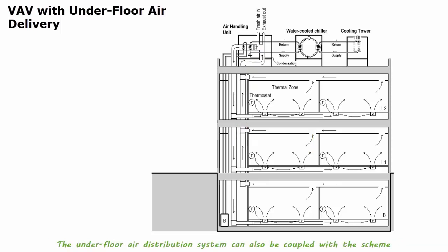The underfloor air distribution system can also be coupled with a scheme in which one local air handling unit is provided at each floor to reduce duct run and fan power.